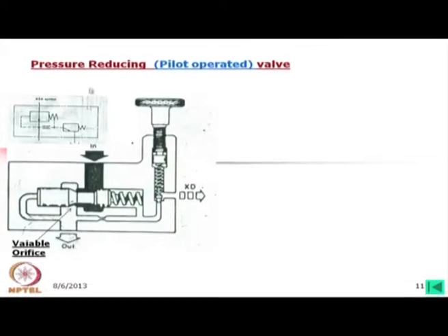That means, in this line there is a pressure relief valve. You will find whatever flow is not being utilized, it is going through this relief valve. This means that we can regulate this pressure, but in this side the pressure will remain the set pressure of the main system relief valve, that you should remember.